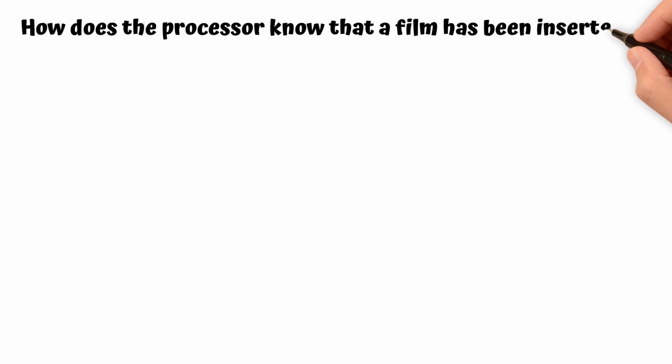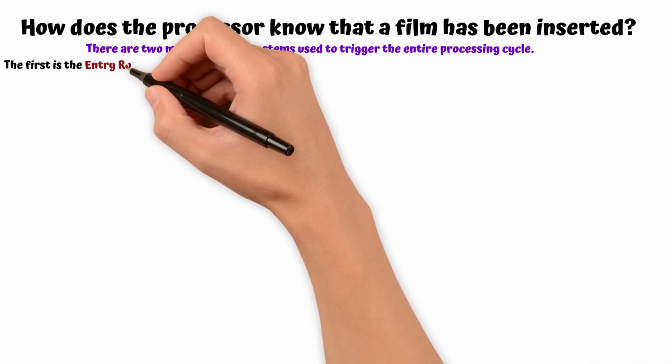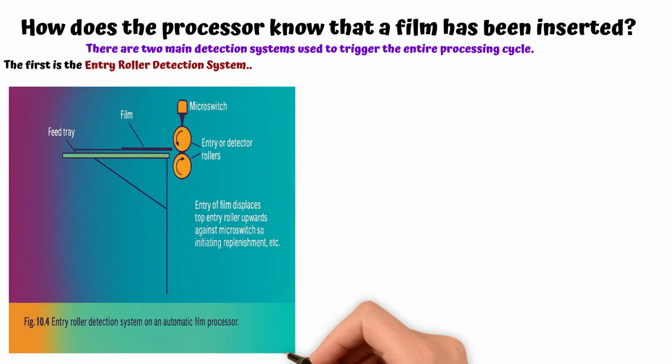There are two main detection systems used to trigger the entire processing cycle. The first is the entry roller detection system. In this system, as the film is pushed against the entry rollers, the upper roller moves slightly upward. This movement activates a set of film detector microswitches, typically 3, which immediately initiate the processing sequence. As long as the film is passing through the entry rollers, these microswitches remain engaged.